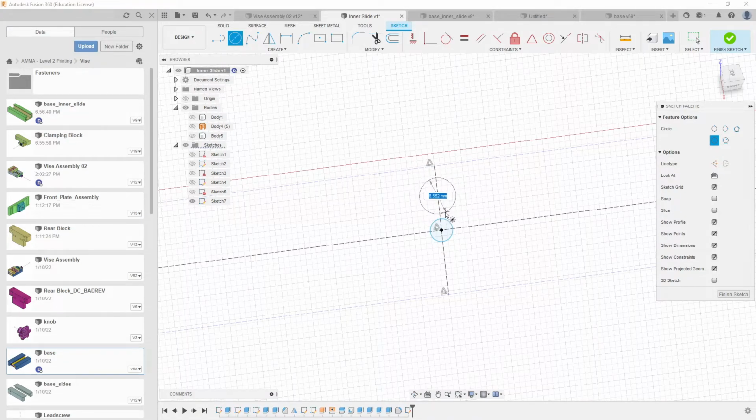And then you also don't want to snap, you see that right there? It wants to snap to that other circle. Don't let that happen. Again, if you're in tight quarters where it seems like it wants to snap to lots of different things, hold down Control. So I click, let go of Control, hold down Control, click again.